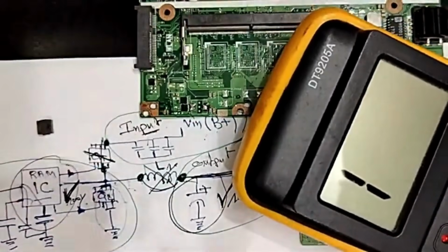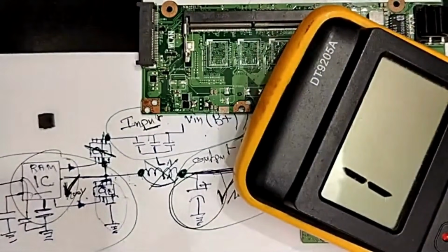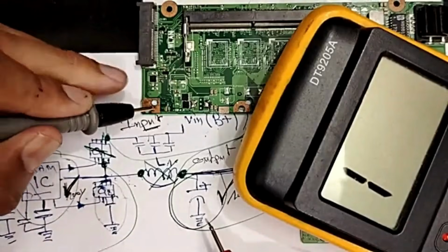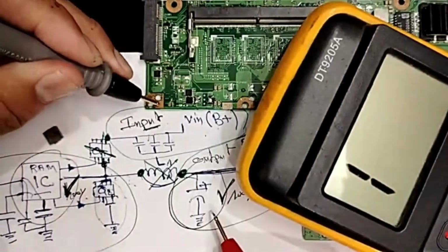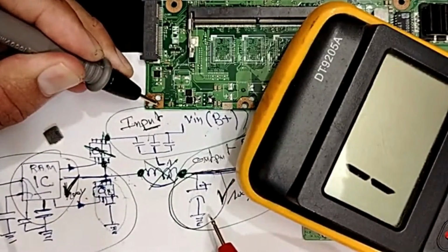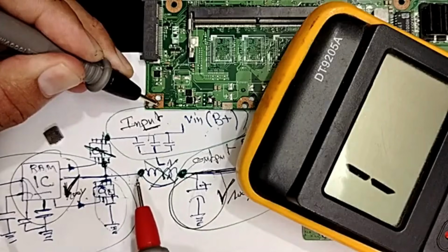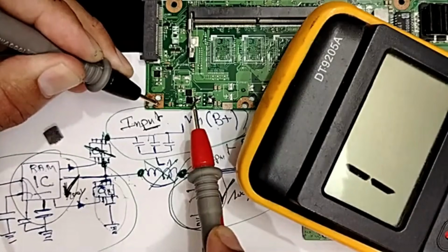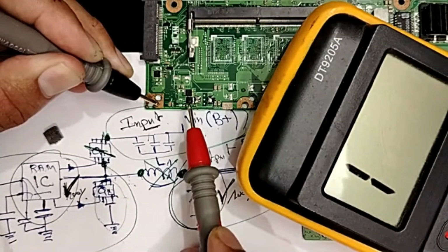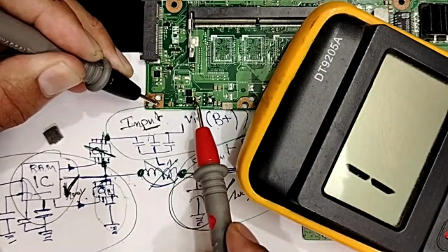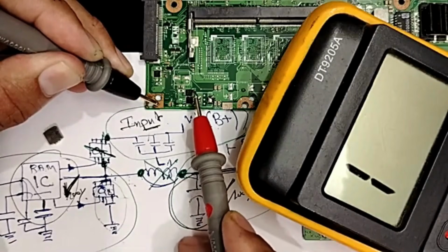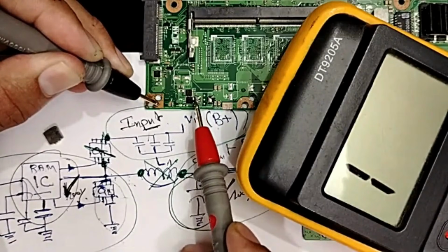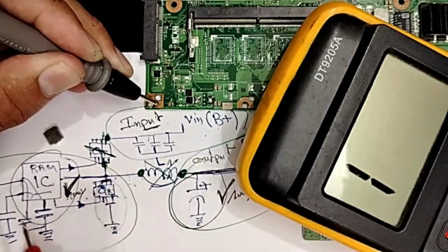Okay, the multimeter here. Let's check, guys. So, one probe here in the ground. Okay? Are you ready? I will check this side first, after that, this side. This side is this one. No shorts. The short is gone. Nice. The short is gone means the MOSFETs are good. Let's check. No short in the MOSFET. Also this MOSFET, no shorts. This is awesome. Means this side is good.